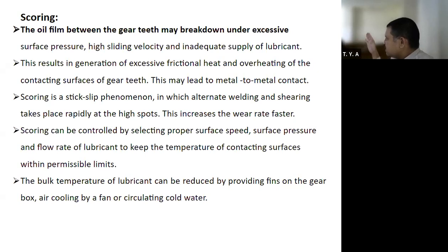The heat is getting extracted, or what is the particular word for that? Heat is getting dissipated, dissipation, from that surface. And also, because of the fins, cooling takes place. Radiators have fins. But if you look carefully at the cylinder and piston in a two wheeler, down there, the cylinder has grooves. Those grooves are the fins, remember. What happens because of the fins? A gap is created. Heat goes out through the fins, and in that gap air circulation happens.